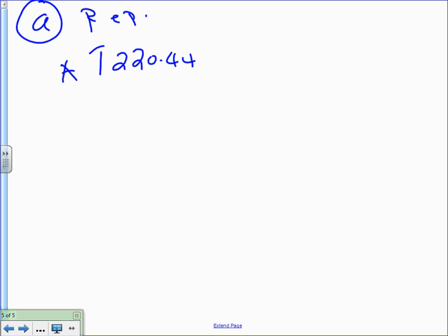Remember, we're still dealing with the A's, which is receptacle and all this good stuff. This one I want to say apply from table 220.44 demand. We're going to apply the demand. The number we came up with was 103.7.